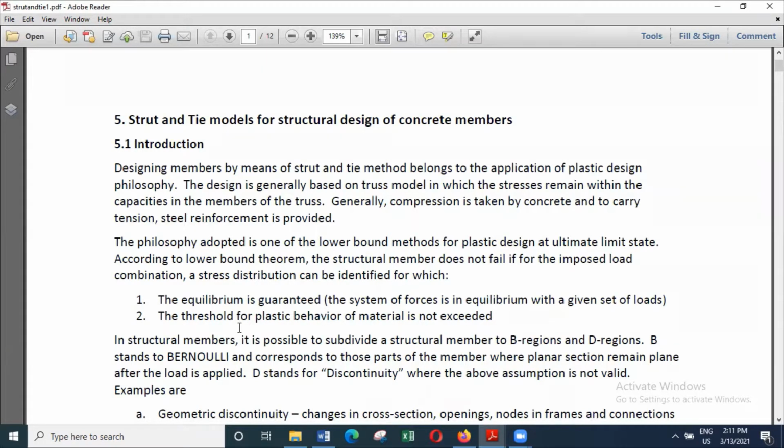But what this theorem says is, if we are maintaining the stresses at sufficiently low levels, and also we are using ductile materials, then we don't have to worry about the actual stresses in the structure. There will be adequate redistribution of stresses if the stress is exceeded at one place, and it will result in a safe design. So that is the theory that we use in almost all the structural members.